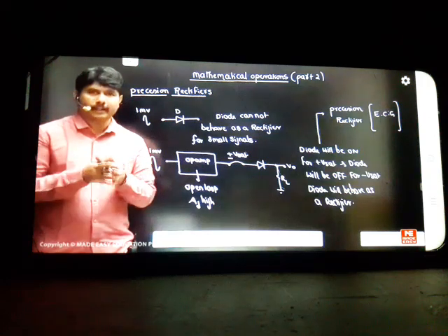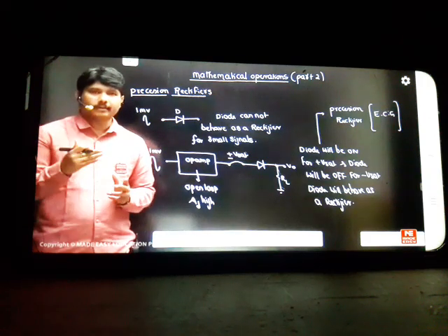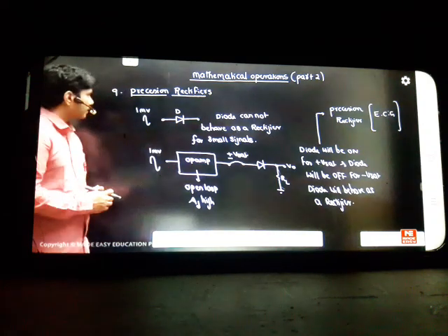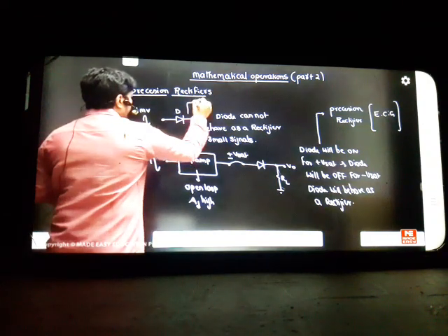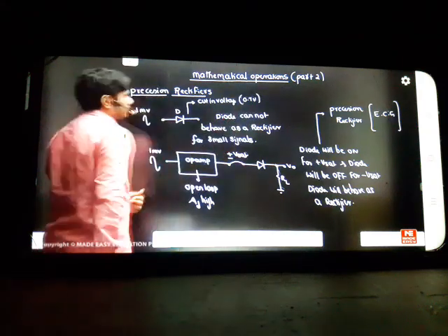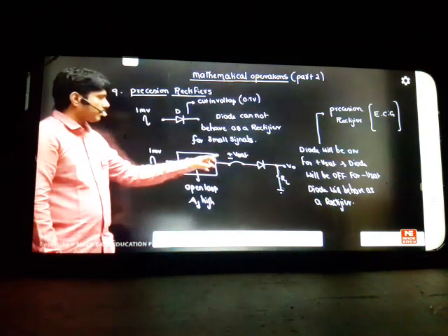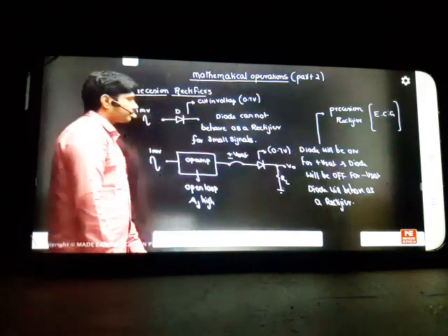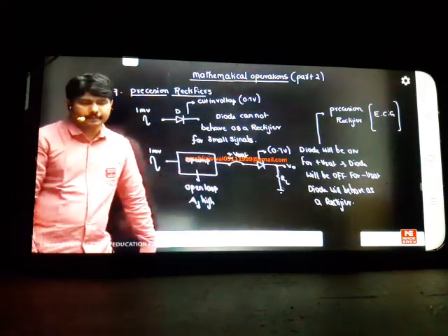Small signals, whenever you pass them to a diode, will not be rectified because the diode does not have an ability to be on, but it has an ability to be off, because a cut-in voltage of 0.7 V is required. Okay, the cut-in voltage of this diode is 0.7 volts. So if you have given only 1 millivolt, it cannot be on. But here it is plus or minus Vsat. The diode cut-in voltage is only 0.7, but my saturation voltage is a very high value, more than this. That's why the diode can be on, can be off. We can do it. Okay.